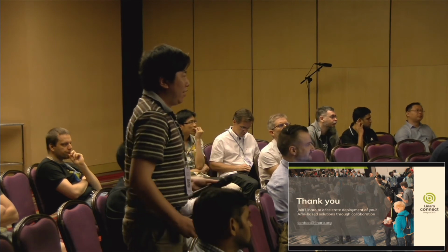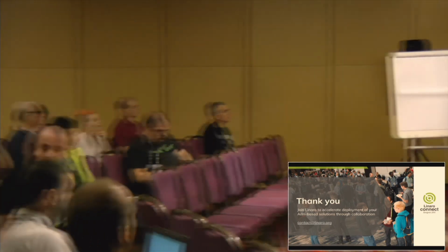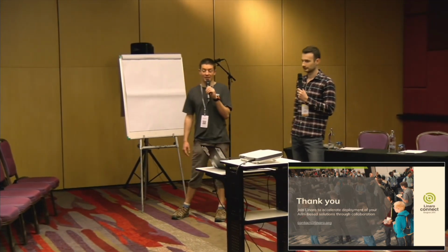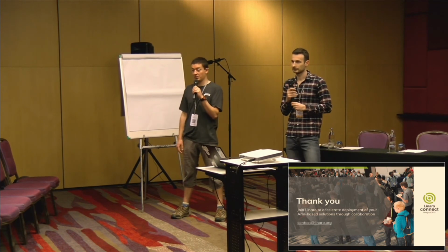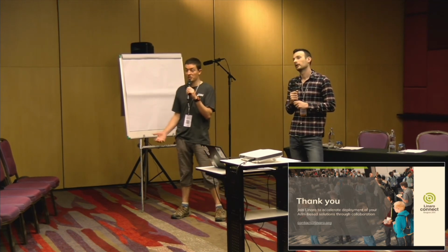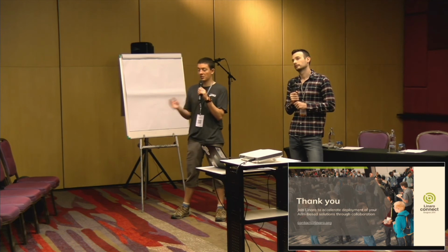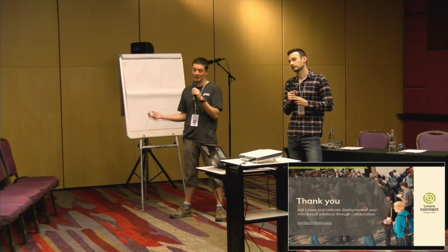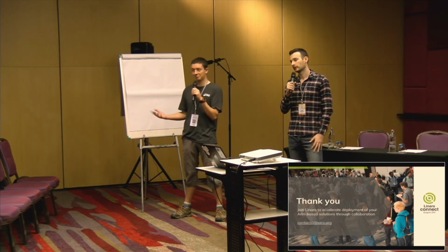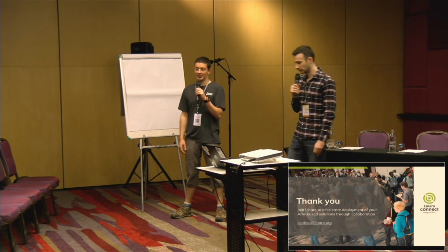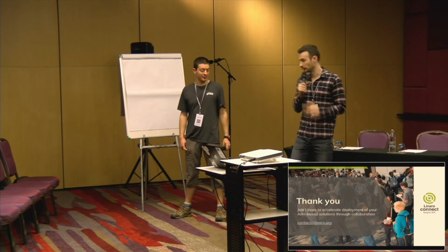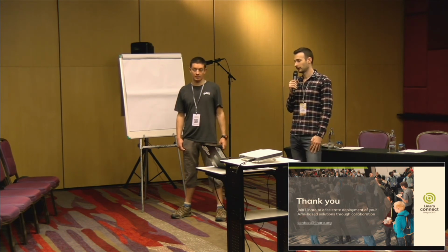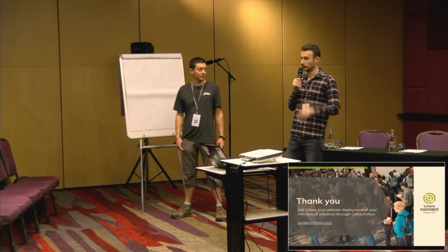Okay, so I will answer backward because I remember backward. Trusted firmware. It all depends on how you flash the trusted firmware. If it's somewhere we can flash automatically, then it's always the same in Lava. If you can do it automatically with a tool which is working on Linux and reliable, then it might be possible. If not, I think it's not. The point is, what he said is that there is no interactive shell, so that can be a problem. And there is maybe no output on the console as well.